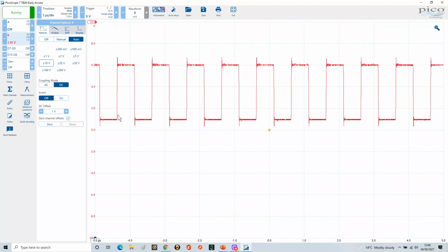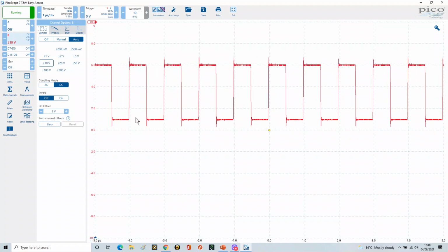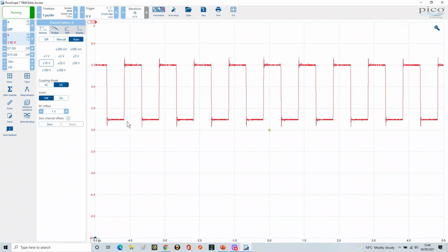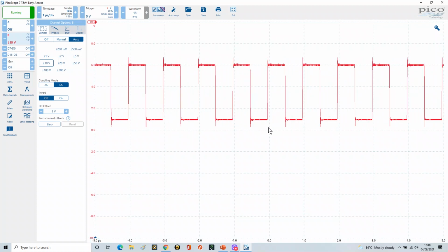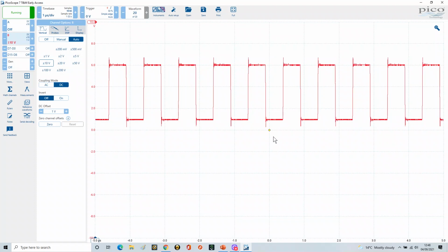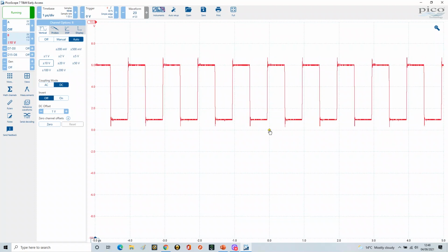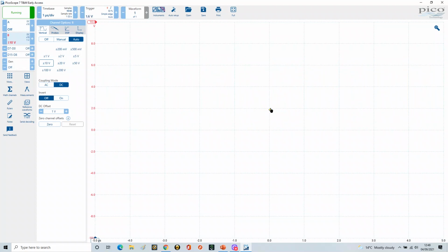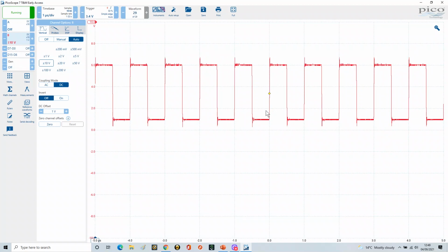Exactly when you would do this within an analytical environment, really hard to know, but there are times when it's actually relevant. What you will notice now is the waveform isn't locked because we're outside our trigger. Our trigger was at 0, but of course the waveform is now out of range. So if I now take my trigger point and move this up here, we can lock it so that the trigger point is in the midpoint of our waveform-ish, and therefore it locks the signal. So we can see the pre-signal and the post-signal against that trigger point. So that's the DC offset.